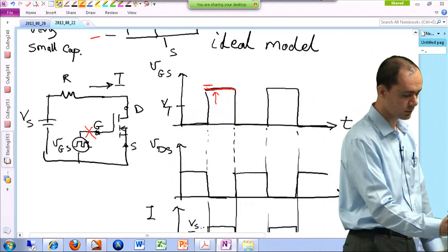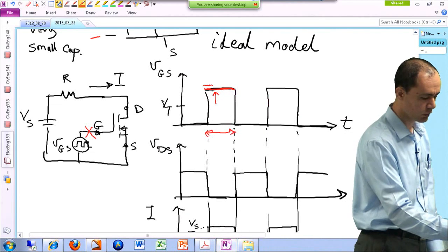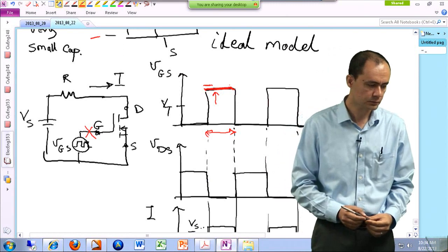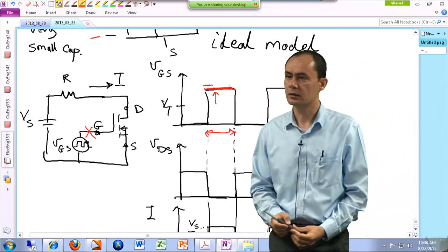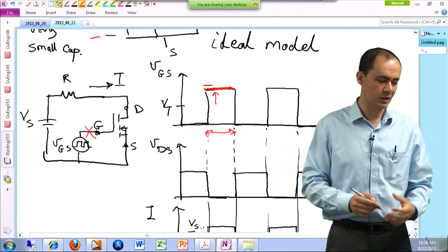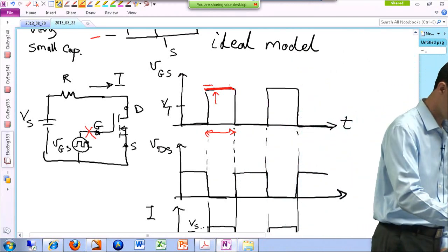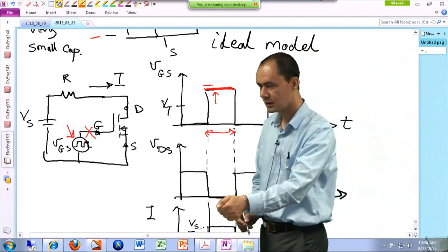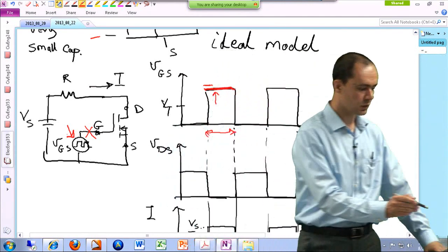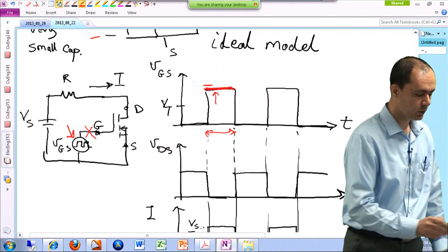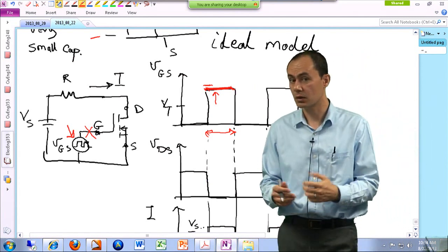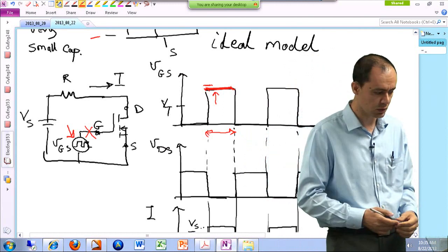So if this conduction is important to you, you have to make sure you are maintaining this gate-to-source voltage throughout that subinterval. This happens a lot in the lab. Students trying to shut down their device first turn the signal generator off, and if the signal was high right before that, your MOSFET is still on. So you have turned your signal generator off, assuming that everything is off in the system, but it is not really off. It is actually continuing to conduct through the MOSFET.